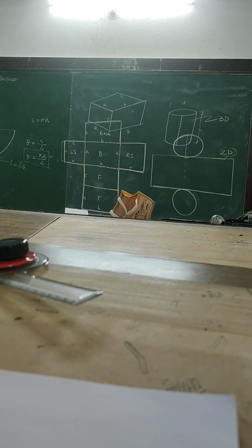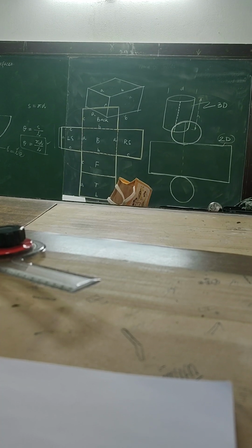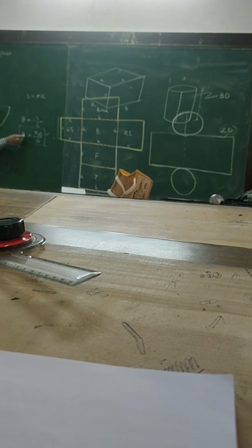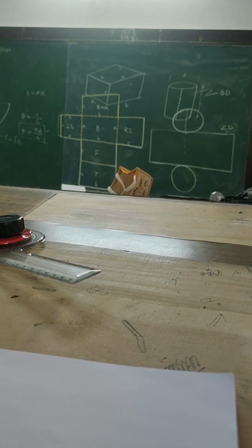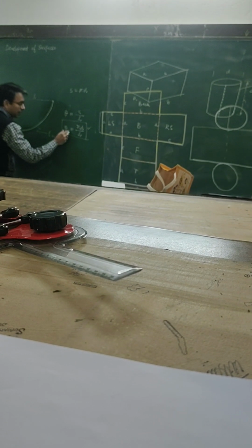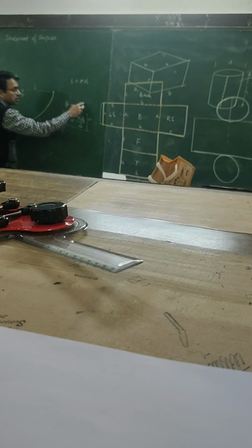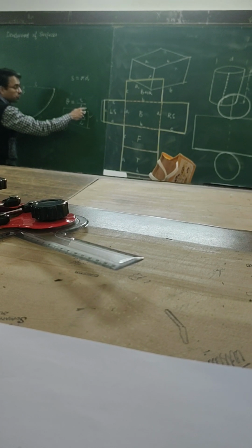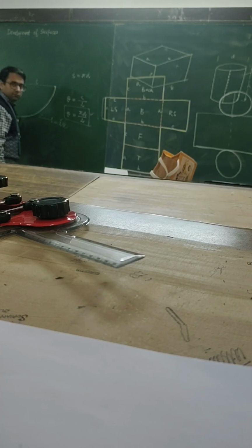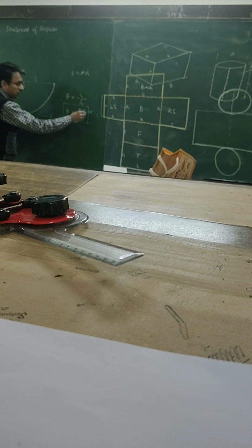So we have this. The final shape is this. We start with this sheet. Then we mark this and then get this length, get this angle from the perimeter of this circle, therefore pi d, and we know this length, therefore the angle in radian, because this formula is for that, that means two lengths are having the same unit as that of length, and this is radian. So pi d by L. Okay. So you know d, you know L, therefore you can determine this.